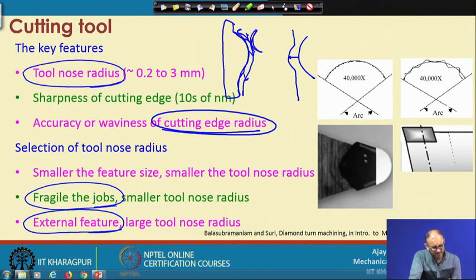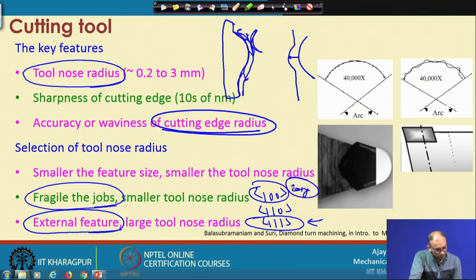Then we have to find out, because with diamond you can do machining with different planes available: the 100 plane, 110 and 111 plane, which we have seen in terms of silicon in some lectures a long time before. We have seen that one is very difficult to cut and another is very easy to cut. If cutting is easy, that means its wear is also very high.